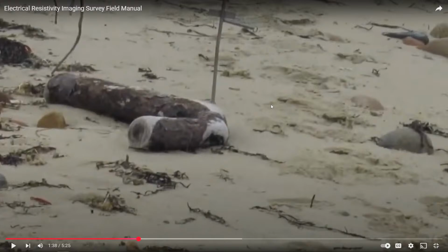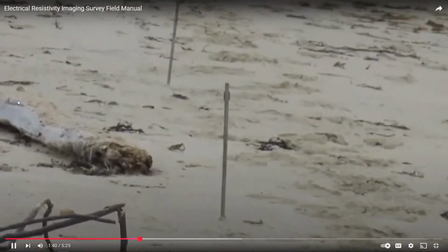For the equipment we have here, mainly many of the aquifers that we are interested in here in this region are at shallow depth. So the interval we have for the instrument, which we will use in the field trip, is 2 meters apart. So the electrodes are placed 2 meters apart, but you can place them any way you like. You can place them 1 meter apart by just coiling them around. And our cable is unrolled along the parallel.